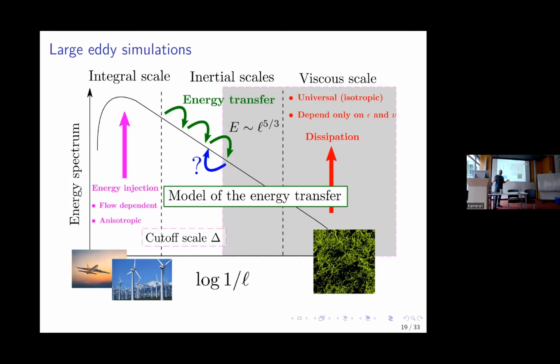this might be okay for modeling, because what I want to model is usually the large scales, because you can get a lot of information from the large scales. You can get friction coefficients, you can get the dissipation, you can get the energies. You're most of the time interested in the integral scales of the flow, and they can describe quite well the behavior of a fluid. And so now if the entropy is driving the cascade, and the entropy is a very strong force, I will not allow anything to go all the way back. This means that I can actually have some success at trying to model the energy cascade.